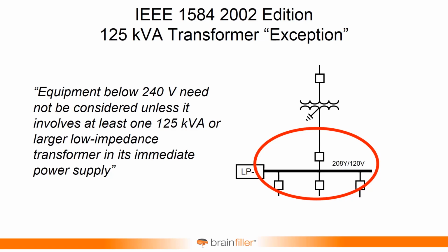Normally what you're going to do is look at the duration of the arc flash being defined by a device upstream, which would be a primary. And you start looking at how long it takes a primary device to operate. It could be a while. And so you could end up with some pretty extreme numbers for your incident energy calculations that may not be realistic. And that's why this was placed in here.